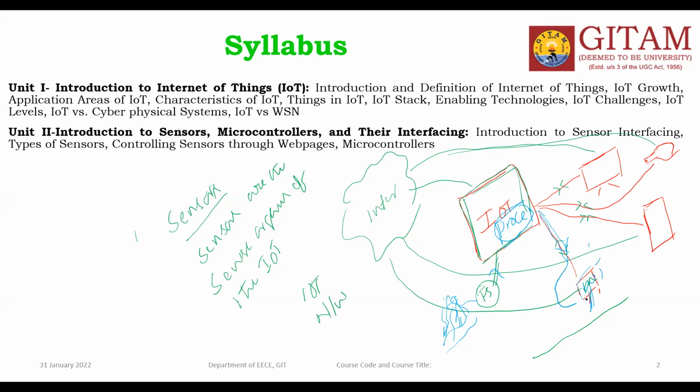When the smoke is detected, the sensor sends the signal to the processor, which processes and sends the control signal to the water tank's control valve. Then it opens the valve automatically, and water will come. If there is no smoke, no control signal, the valve does not open.